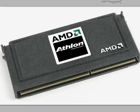But when you take a look at the processor itself that would go into that, now it starts to make a little bit of sense. These are single-edge connector cards, and they would have a notch here so that you could not put them in backwards. And this used to be a design that was implemented by AMD, and Intel also had some of these as well, but not too many. These kind of had a short life. They didn't last too terribly long in favor of other socket designs, which I'll talk to you about next.